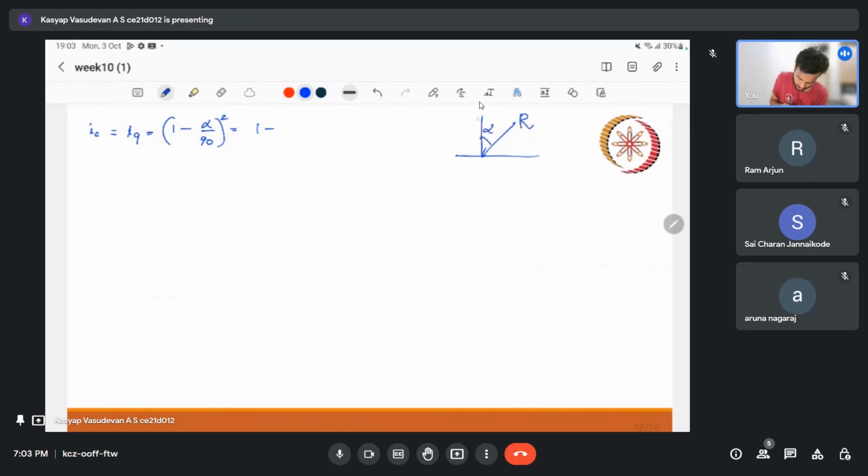I have vertical and I have horizontal, so I can write alpha as tan inverse of horizontal by vertical. That is tan inverse of horizontal load, 95.62, over the vertical load sum, 268.34. If you substitute this, you will get alpha as 19.61.